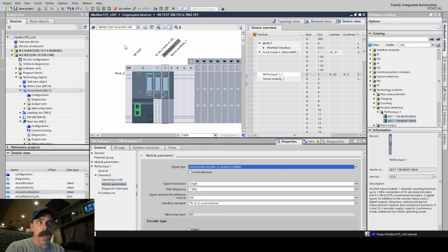I believe it's a 20 and a 30 encoder, an SMC20 and an SMC30, and that's part of the S120 system. So if you want to bring in one of those, there's a way that you technically don't have to have an actual module out there, like a motor module and a motor. If you're just wanting to bring in an external encoder, there is a way to do that. It's not really straightforward.